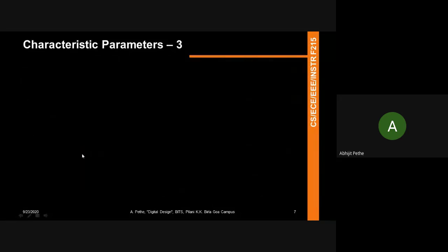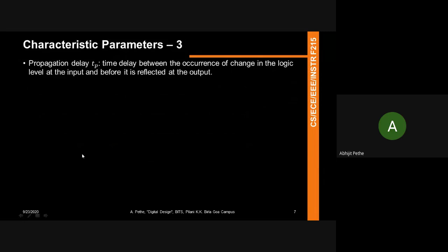All right. So remember again, propagation delay is an important concept: input change to output change, right? For example, suppose you think about a NAND gate, and suppose I've given one input as a 1, and I call the other input A. So when A is a 1, I know the output is a 0.